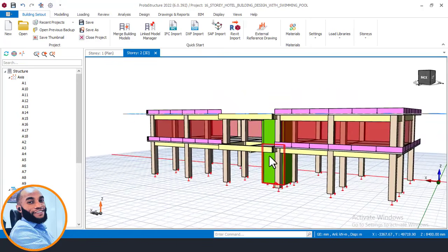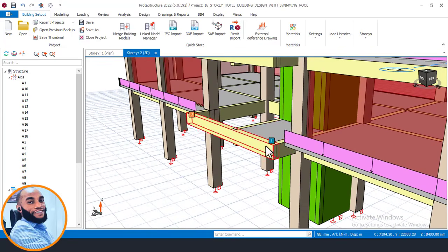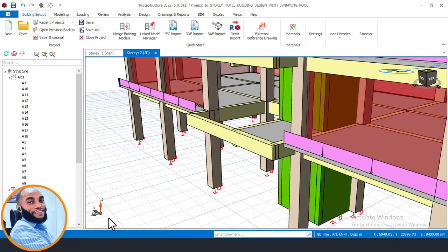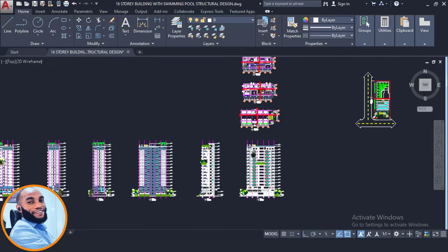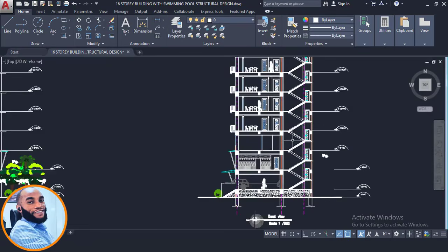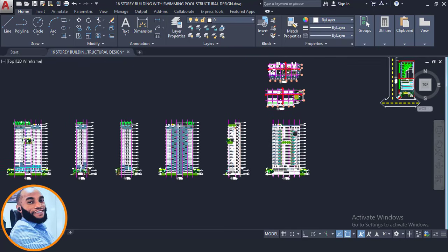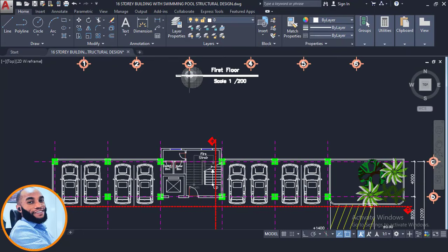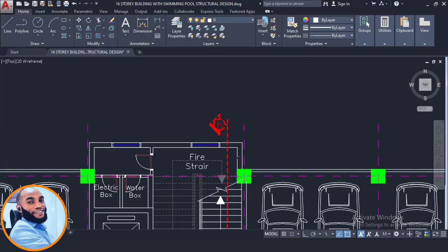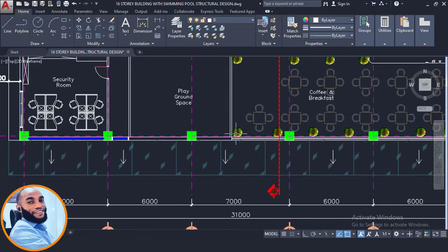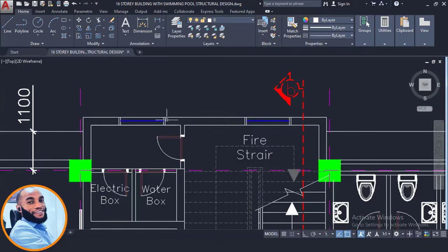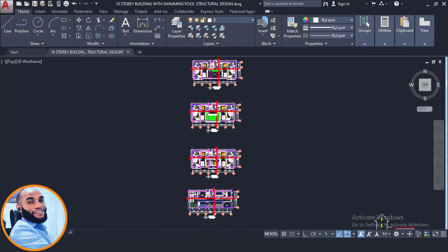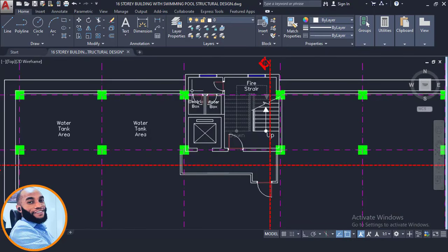Okay, so let's confirm from our CAD file if this one here has a wall load or not. This is the area on the CAD file. This is the back view, and from what I'm seeing right now, there's a window here. So since there's a window, there's a wall load around this place, and it also continues. Let me check again. Yes, it all has windows, so there should be a block wall around that area, around the cantilever beam area.